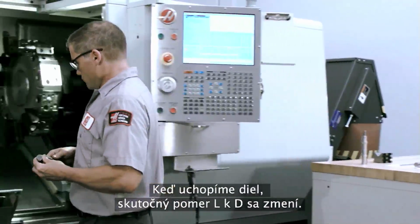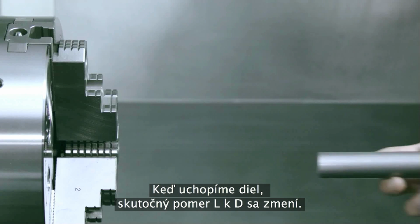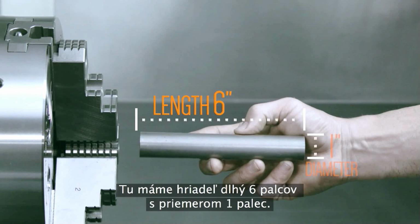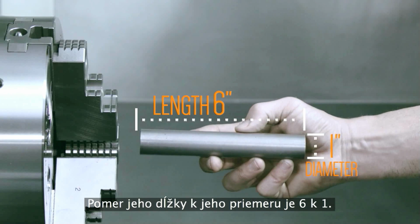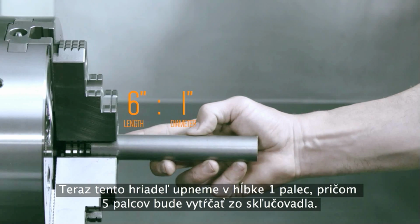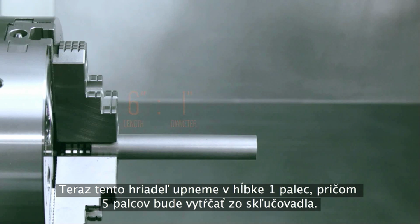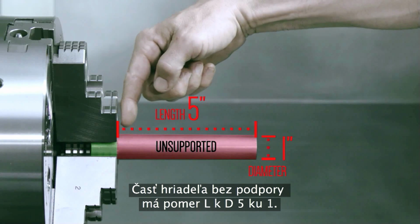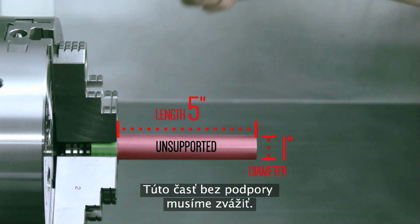When we grip the part, the effective L to D ratio changes. Here we have a 6-inch long by 1-inch diameter shaft. Its length to diameter ratio is 6:1. Now we clamp this shaft 1 inch deep with 5 inches extending outside the chuck. The unsupported region of the shaft has an L to D of 5:1. This unsupported region is what we need to consider.